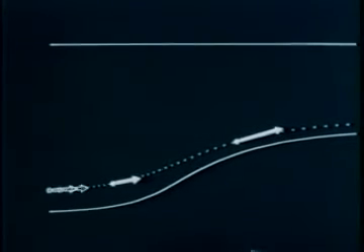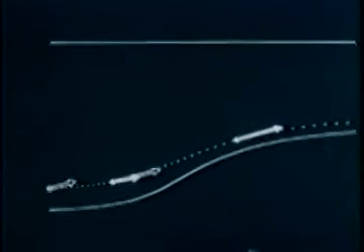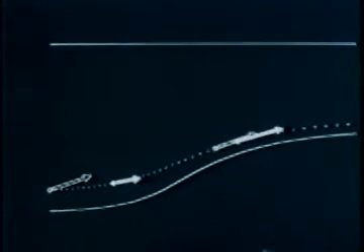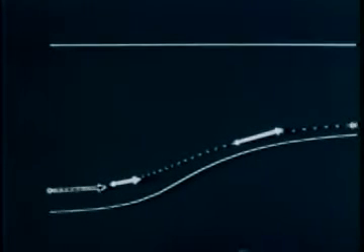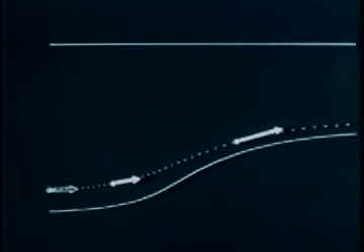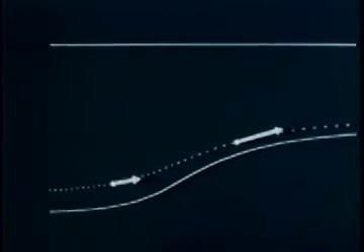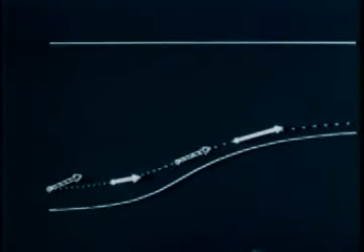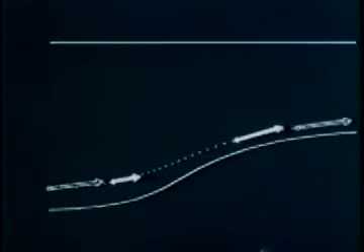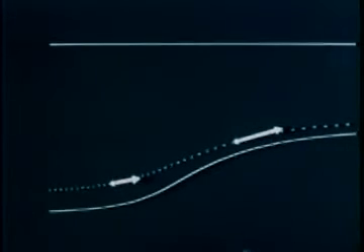Although the physical field is the same, the Eulerian and Lagrangian representations are not the same, because the velocity at a point in laboratory coordinates does not always refer to the same piece of matter. Different material points are continually streaming through the same laboratory point. The velocity that a fixed probe would see is the velocity of the material point that is passing through the laboratory point at that instant.